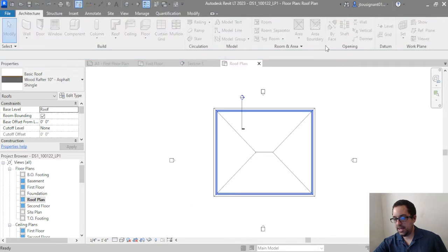And if I press check, it's going to ask if we would like the attached highlighted walls to attach to the roof. That means, do you want your exterior walls to attach to this roof? This isn't an always attach or an always don't attach. Just like this dialog box isn't an error, which is why I typically never click the do not show me again buttons, because this can be a different answer depending on your situation. So I'm actually going to click attach for this, because in this situation, I will want these exterior walls to attach.